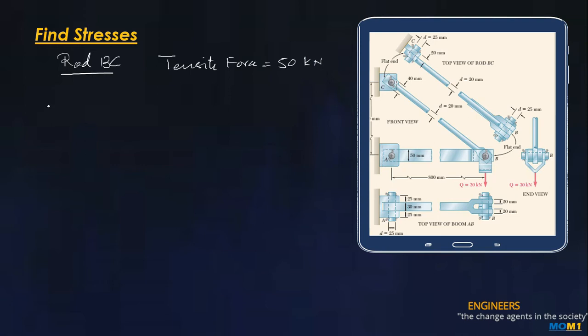To calculate the stresses, we have the expression sigma is equal to force upon area, and we can calculate the area because we have the diameter of 20 millimeter.